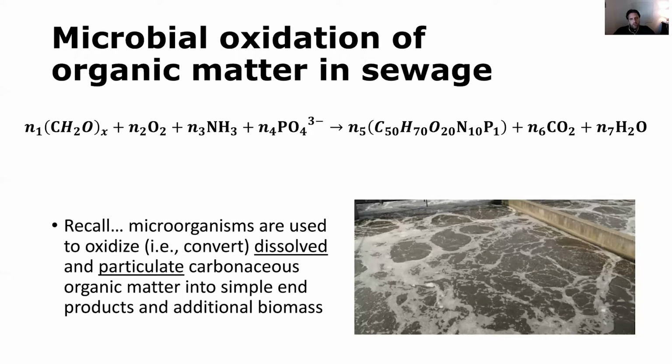So again, getting back to municipal wastewater treatment, which is mostly domestic wastewater, we are talking about the microbial oxidation of organic matter in sewage. Unlike water treatment, where we're mostly using physical chemical treatment processes, for wastewater treatment, we rely mostly on biological treatment processes. So essentially, we're letting the microbes do the work for us. Microorganisms are used to oxidize, converting the dissolved and particulate compounds into simple end products and additional biomass.